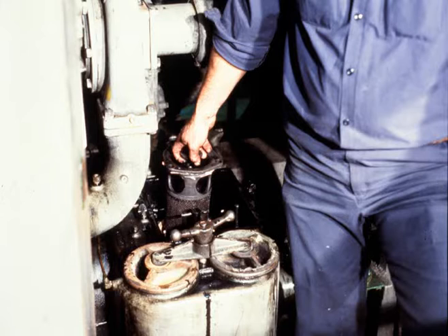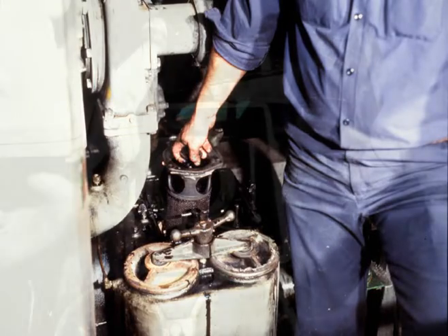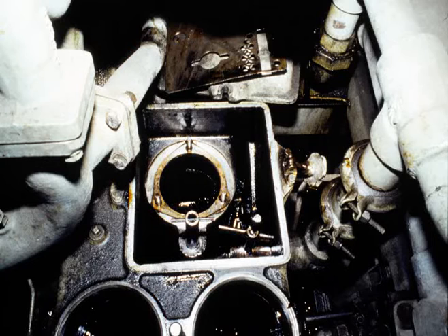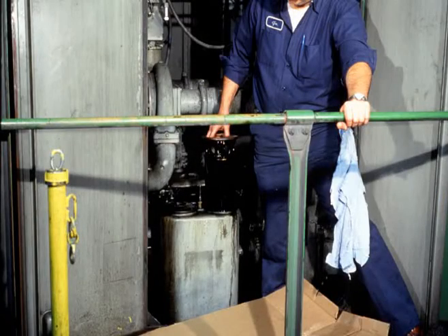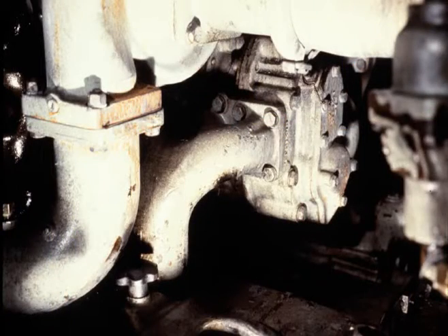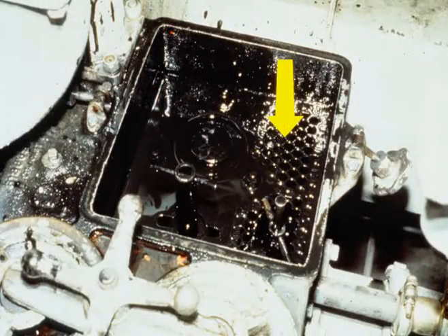If the oil level drops below that level and remains there for more than 45 seconds, the scavenging system is likely defective. A good place to look is the gasket surface or the strainer not drawn down on the gasket. If the oil level rises above the screen and remains there for any length of time, either the two strainers in the housing are plugged or the piston cooling or the main lube oil pumps are not drawing from the housing. If the oil level is constant, the pumps and strainers are operating normally.